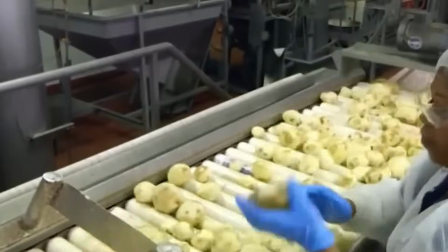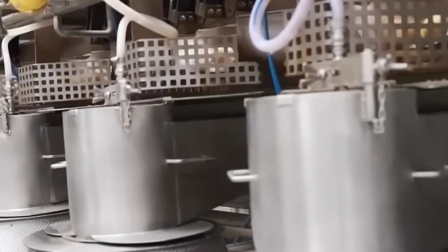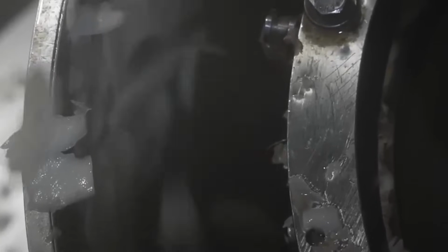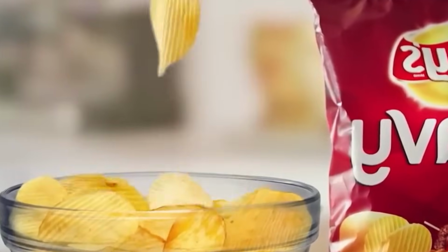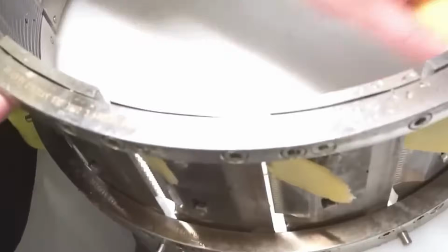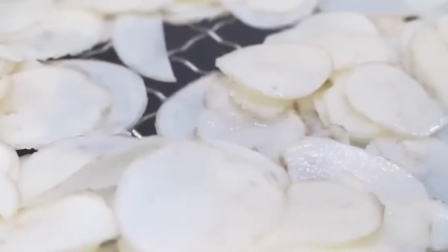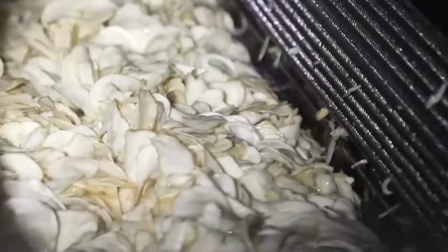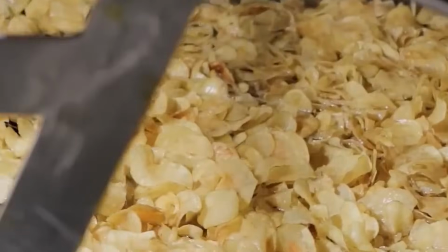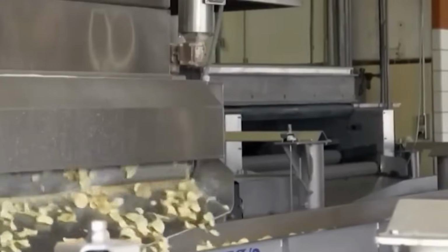Multiple bags are grouped together using timing belts and dropped into pre-formed cartons or display trays. Automated case sealers close and glue the boxes. A print and apply labeler affixes tracking labels with batch number, expiration date, and barcode. Cartons are conveyed to a robotic palletizer that stacks them according to pre-programmed pallet patterns, optimizing space and transport efficiency. Full pallets are wrapped in stretch film using a rotary arm or turntable wrapper. A barcode label with product and pallet ID is applied.